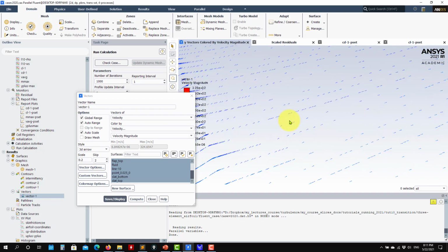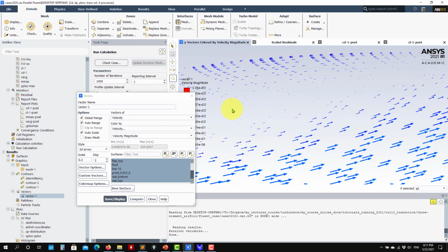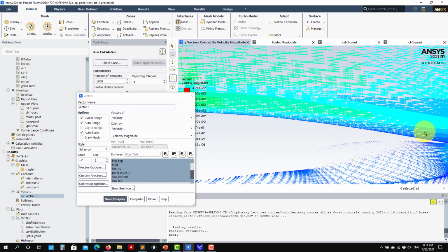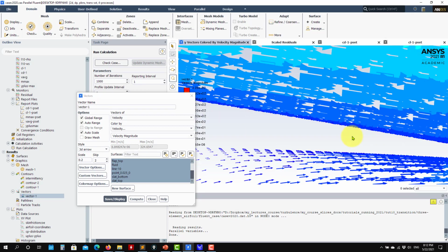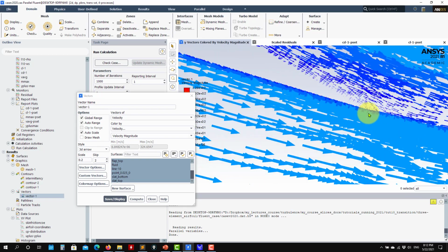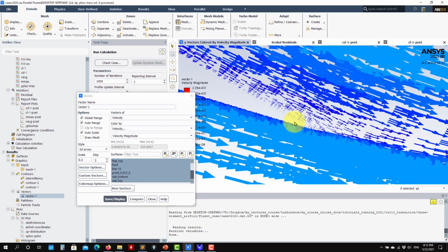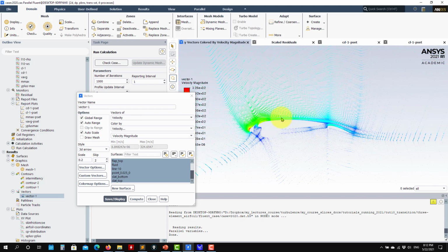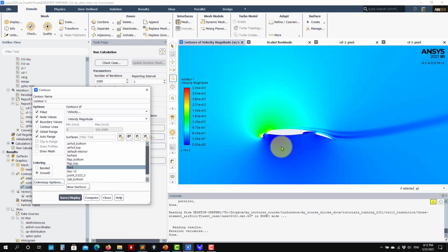So see that it's a large angle, and you have the behavior here. Kind of very nice recirculation here as expected. Then see that you also have, I think somewhere you will see that the boundary layer is detaching towards the trailing edge. Then you analyze the flow, and you just need to give it that physical interpretation. See here that you have the separation. In reality, for this angle of attack, there will be massive separation. Remember here the averaging and everything. We are smoothing, let me use that term, we are smoothing the physics. Okay, so that's all for this case.